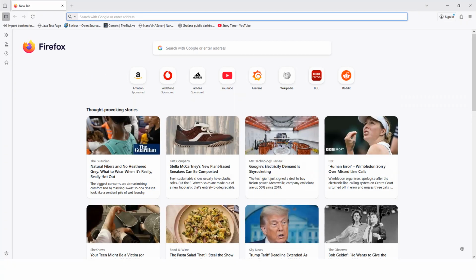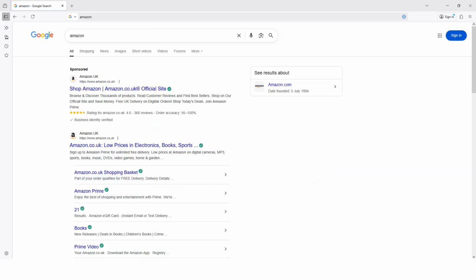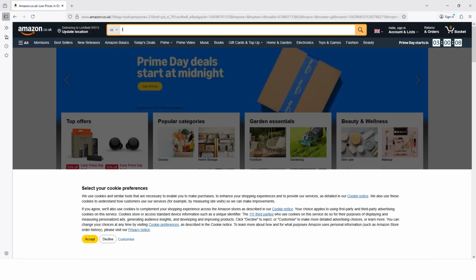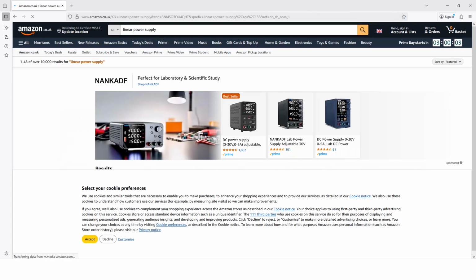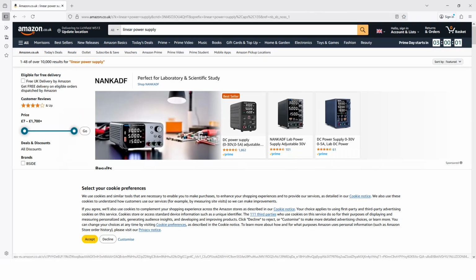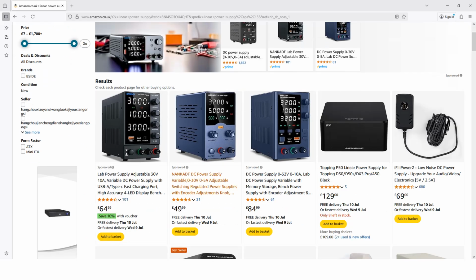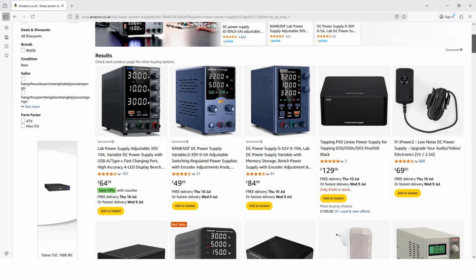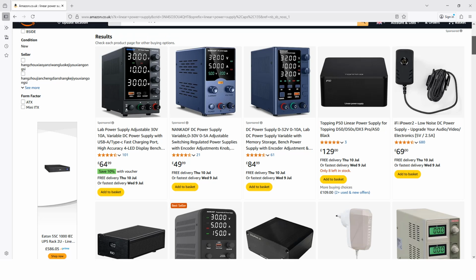Yeah. So what I would do is just go for a linear power supply. Use linear regulators, and just go old-fashioned with a linear regulator power supply. If you need 5 volts, the old 7805 linear regulator chip, and just build yourself a nice linear power supply and stay away from the switching power supply. I tend to hear the power from your USB is not that clean.